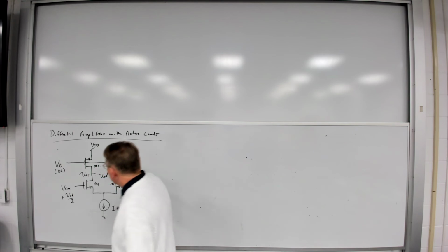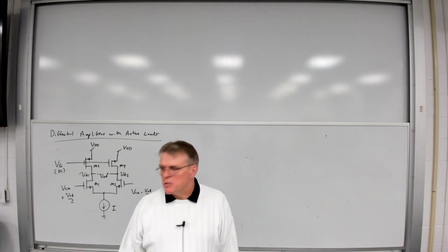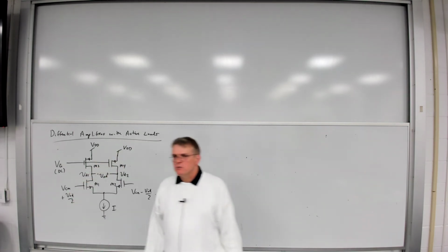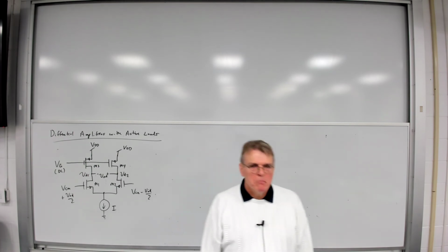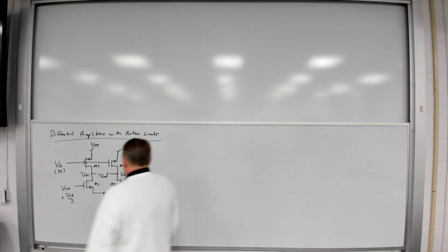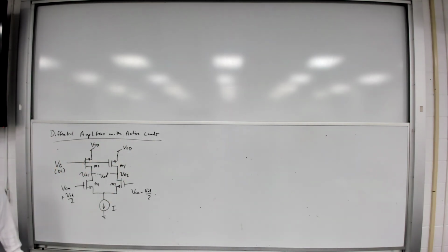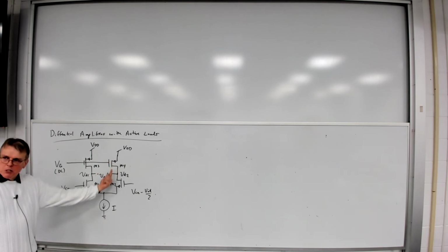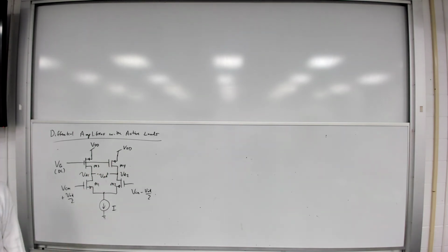So in this case, I'm replacing the two drain resistors with two transistors biased as current sources. A couple of PFETs as current sources. Now I can go through and do the small signal diagrams. The difference is now what resistance do I see looking up into the drain of that current source device? What's it going to be? It's a little R sub O, isn't it, right? It's the output resistance, the R sub O, 1 over lambda ID.